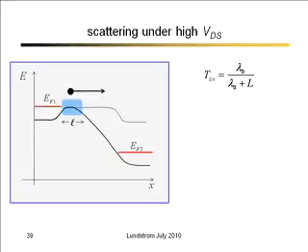So really, the only thing that matters in terms of electrons getting from the source to the drain is their probability of transmitting across that bottleneck regime. They can scatter in the drain. That'll slow down the dynamic response a little bit, but you're still going to be sub-picosecond, over terahertz frequencies. And DC-wise, you're not even going to see any difference. So what we have to do is to replace the channel length by the length of this bottleneck under high bias. And the point is, under high drain bias, that bottleneck is a small fraction of the channel length, which is why you're able to get closer to the ballistic limit.